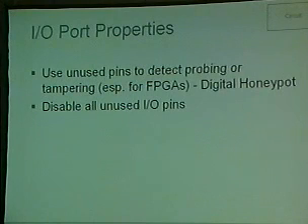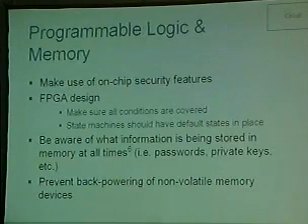What you could do, especially in FPGAs, is set some of your unused pins to detect probing, which is what we call a digital honeypot. You set the pins as inputs, and if you detect a level change, possibly if someone pulls a pin to ground, the FPGA will know that, and you can assume the device is being probed, and the circuitry can handle that properly. And that's a low-cost method that can be implemented.